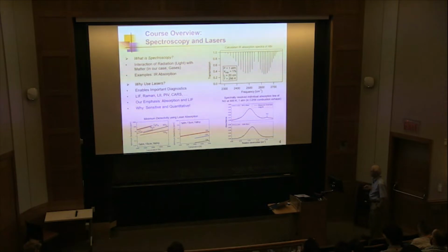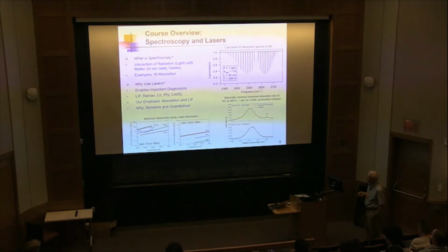These lower left-hand plots are plots of the detection limit in parts per million for different species. You'll see there we've got some, I'll call these small molecules. And you'll see that if we have a 1 atmosphere experiment with a 15 centimeter path length across my shock tube, megahertz time response, we can detect in the range of 1 to 100 parts per million of those species.